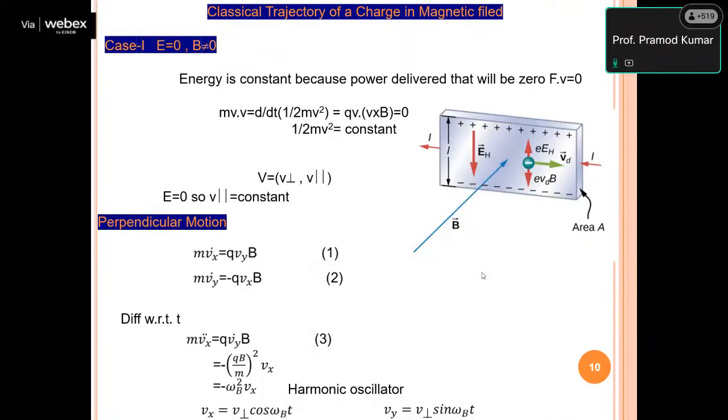Now try to remember what we are doing whenever we are performing the Hall effect measurement. Before moving on, remember that the classical Hall effect and the quantum Hall effect are different. The classical Hall effect means we are measuring the Hall effect at very low field, normally up to 2 Tesla, not more than that, so you get almost linear behavior.